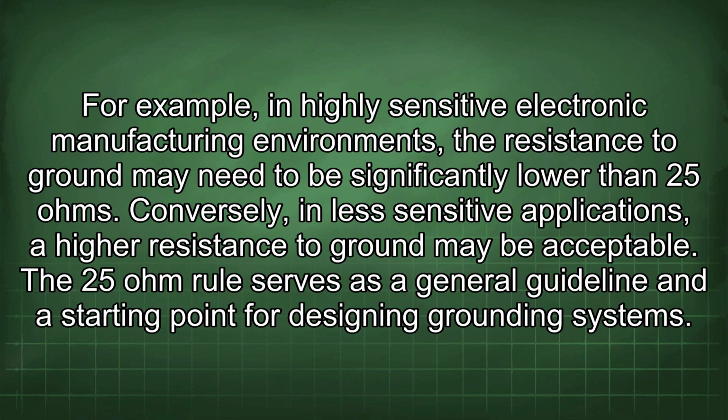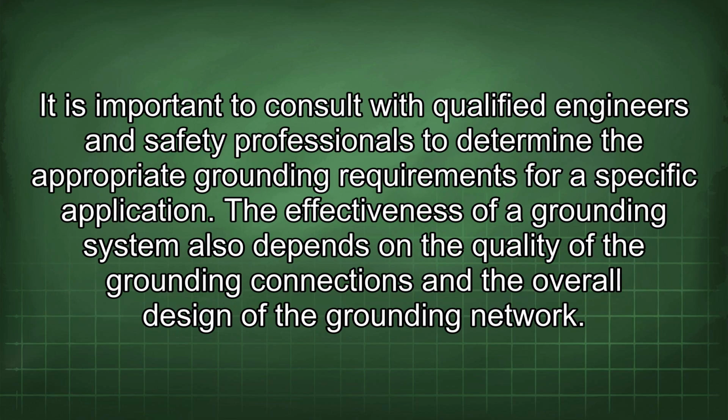For example, in highly sensitive electronic manufacturing environments, the resistance to ground may need to be significantly lower than 25 ohms. Conversely, in less sensitive applications, a higher resistance to ground may be acceptable. The 25 ohm rule serves as a general guideline and a starting point for designing grounding systems. It is important to consult with qualified engineers and safety professionals to determine the appropriate grounding requirements for a specific